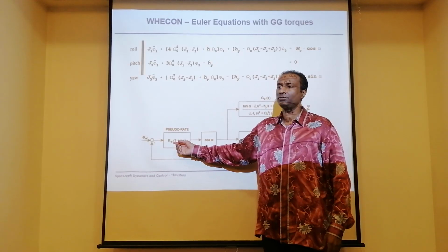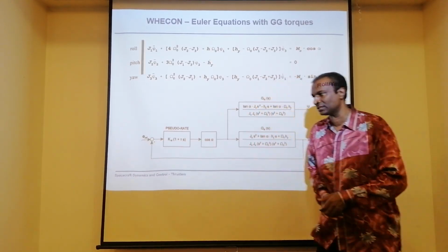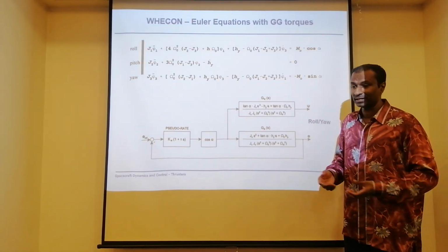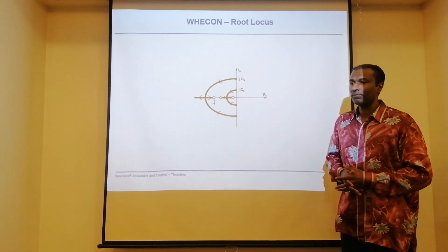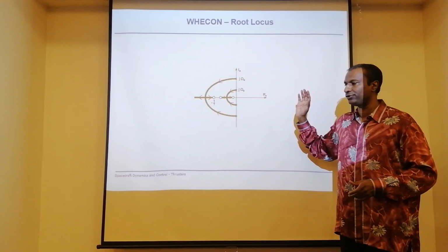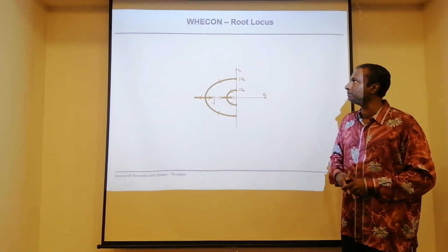You want to look at the gain, that means the proportional gain and the derivative gain. How to actually do that? To select that, we do a root locus. For example, you can do a root locus, you can do a Bode diagram. So in order to find the poles, to ensure the system is stable. This is very typical in control systems.